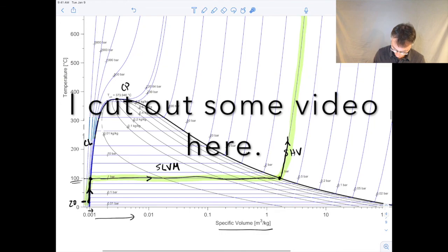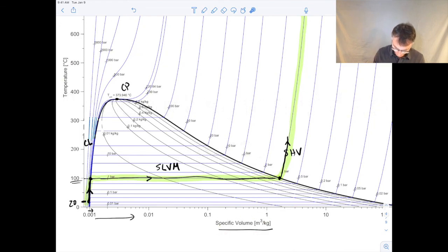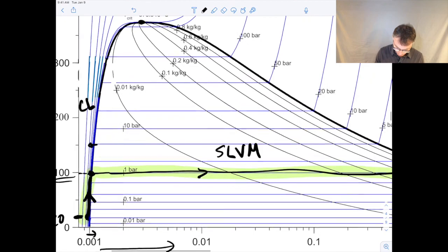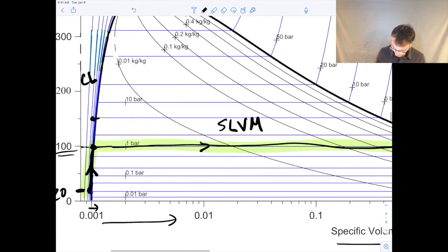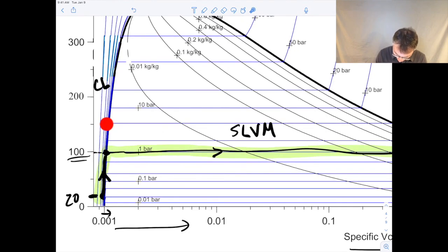So here's temperature versus specific volume for water. You can see these are the isobars. So you can see these isobars are going from 220 bar to 500 to 1,000. I mean, they're going in huge step sizes. But as I change pressure at a given temperature, I don't really move that far in the specific volume axis, right? So again, this axis is specific volume. As I cross these isobars here, the properties don't change a whole lot.